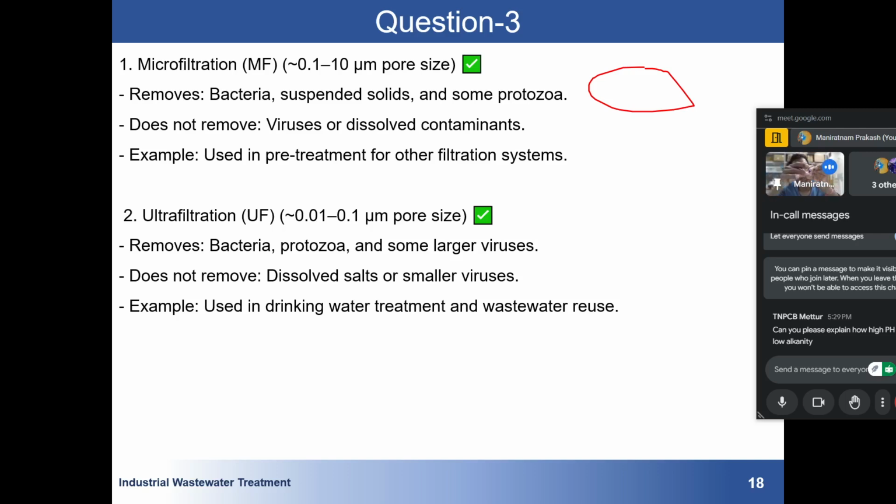It has a membrane filter assembly which has a size of 0.22 micron, sorry, not nanometer, micron. 0.22 micron comes in the range of microfiltration. Generally, we use it to remove dissolved and colloidal particles, so in our sample we want everything in dissolved form.